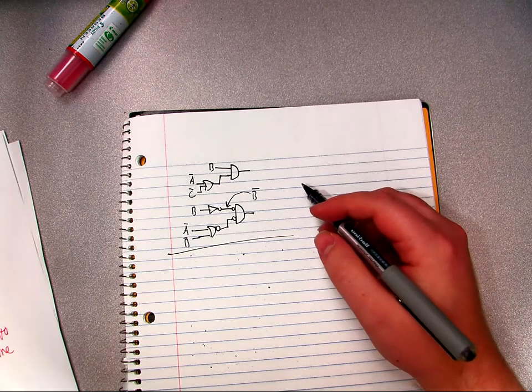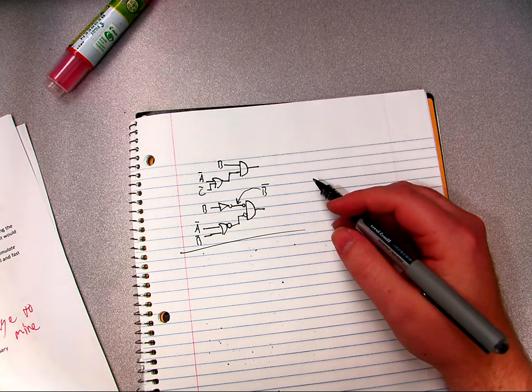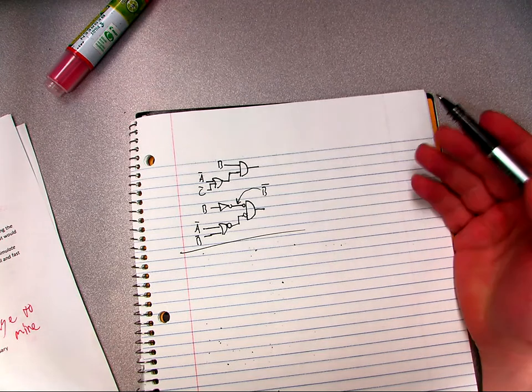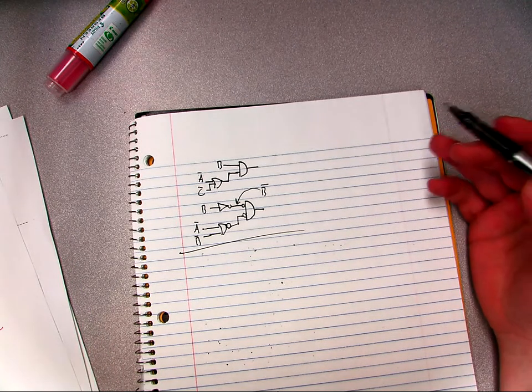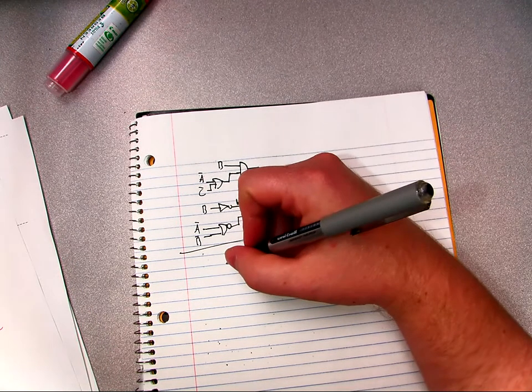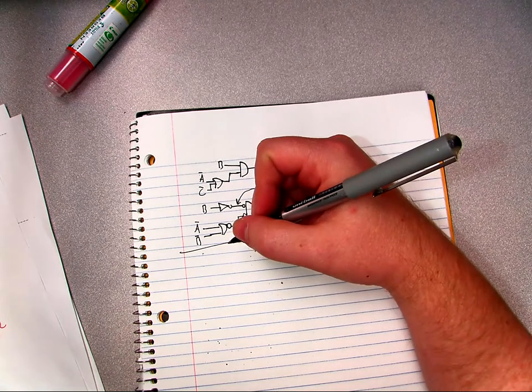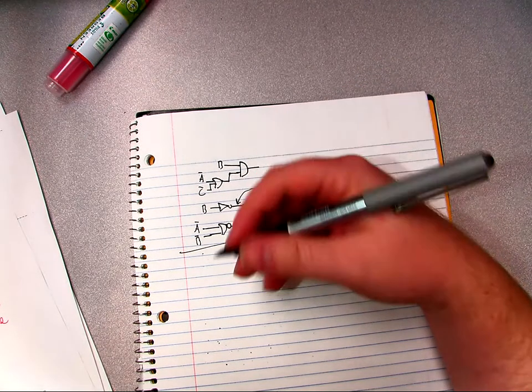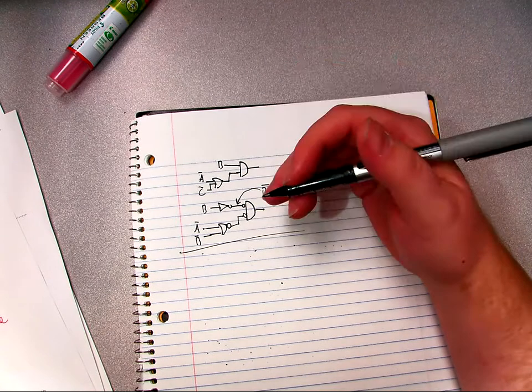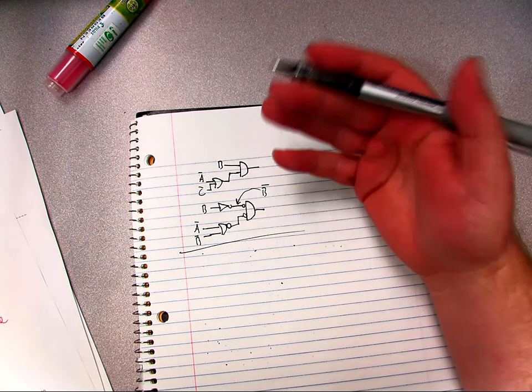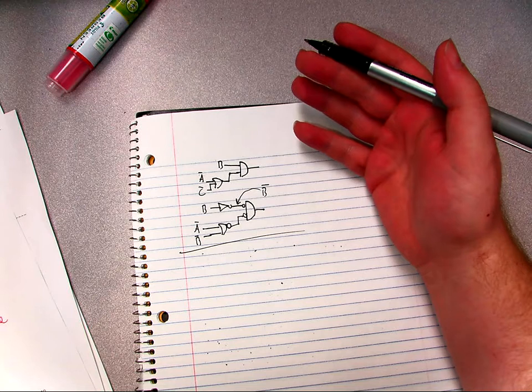You'll notice the first thing I say to do is create the ports according to the handout. The handout in the lab has the ports for the entity that you want to build. That's pretty straightforward to do in VHDL. You can look up examples either in the book or online for how to do it.